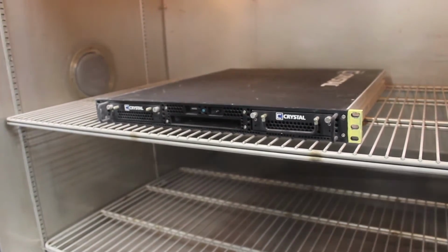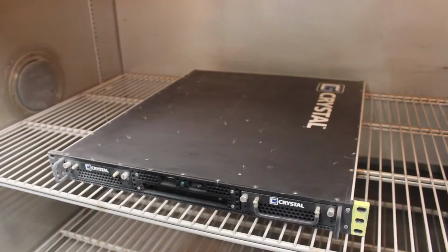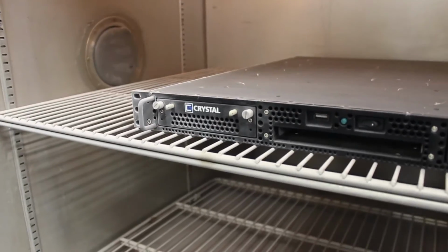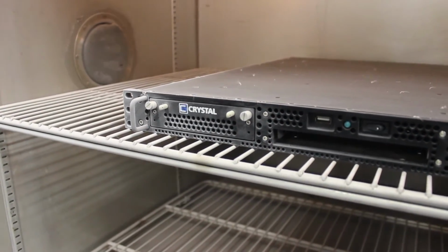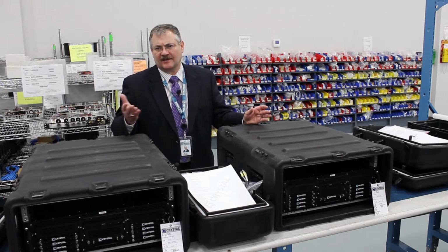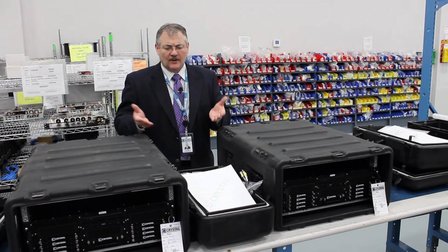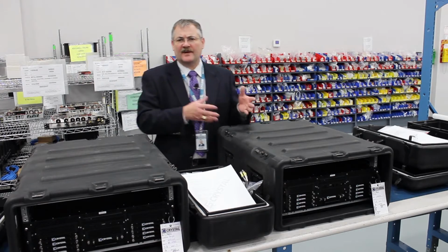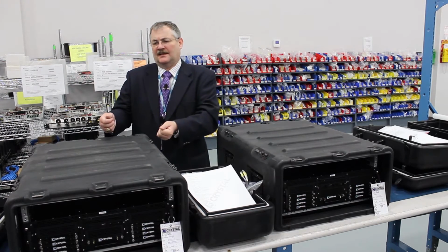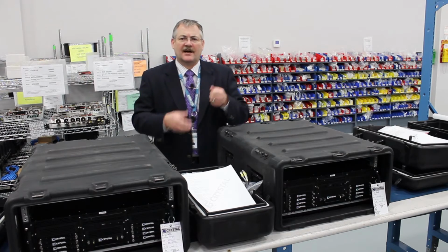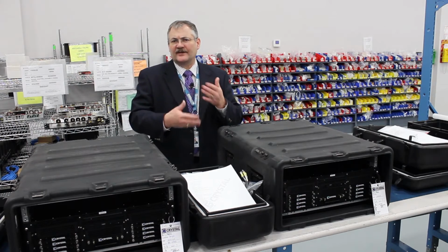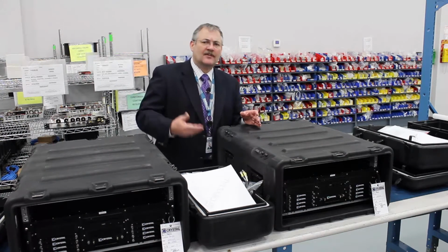And the test defines high-speed transition as essentially 10 degrees C per minute, although that's at the very least 10 degrees C per minute. So you can actually have much more rapid transition in some of these tests. So what is it that you're really looking for when you take your equipment, say, out of a Humvee that's heated and put it into a very cold environment, or out of an air-conditioned room and put it into a very hot environment? And so it's really kind of tailored. The testing is tailored around your specific application needs.